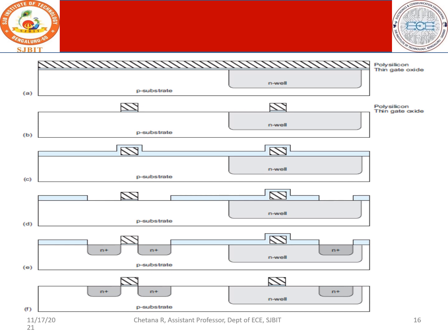So when you have the gate, it is understood that this is the place for your source and drain, and only in this region the N diffusion occurs through a procedure called ion implantation. Once the source and the drain of the P substrate are created, focus is done inside the well structure. So inside the well structure, polysilicon is already created, so create places for your P diffusions. Likewise P diffusions are created in this particular space, 1, 2.